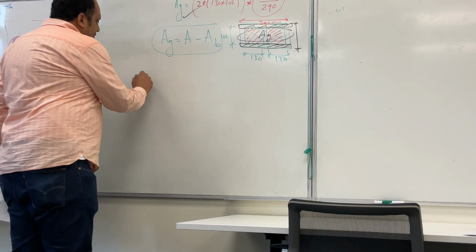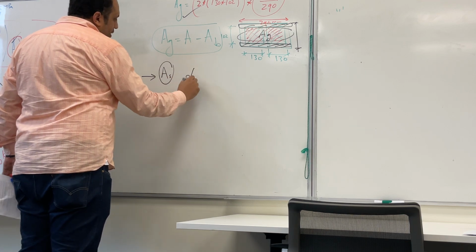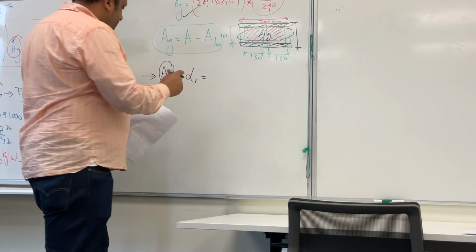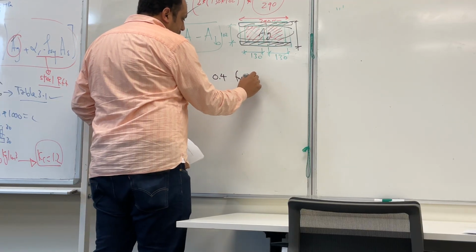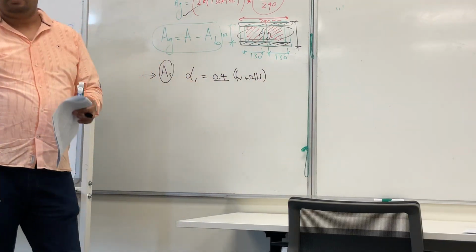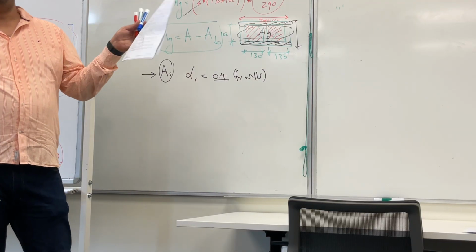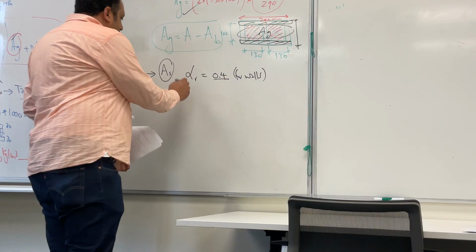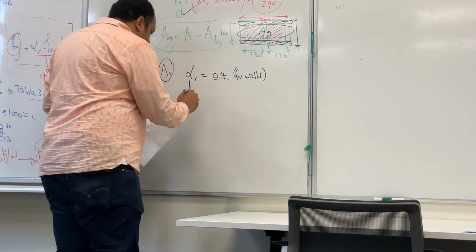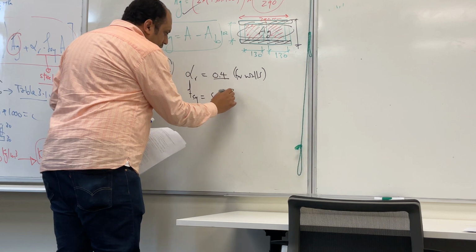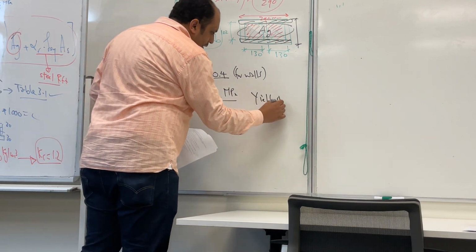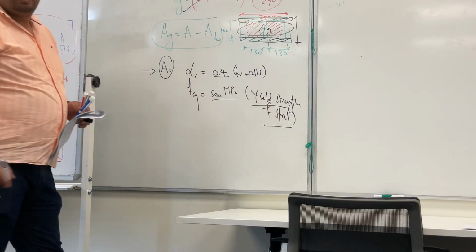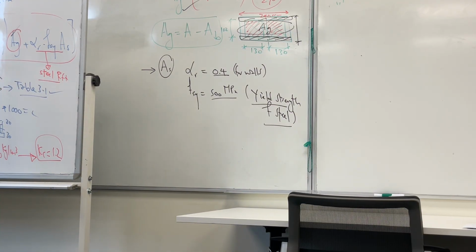So what is alpha R first for the steel? If you remember, alpha R is 0.4 for walls. It can be 0, 1 or 0.4: 1 for beams, 0.4 for walls, and 0 for concentration. What else? F yield. How much is F yield? 500. This is the yield strength of steel. Okay, so now we can get the required As. So how can I find As?